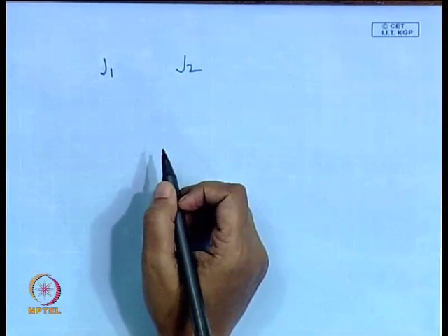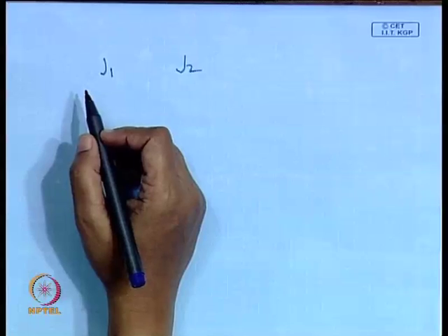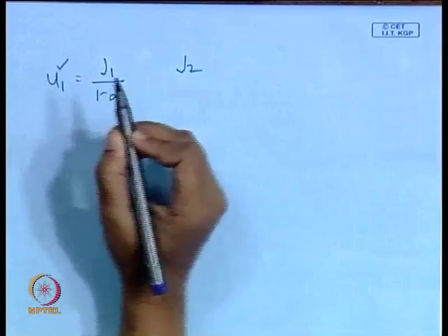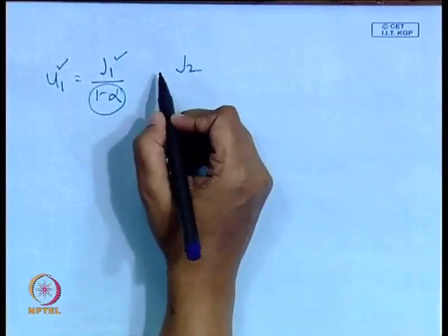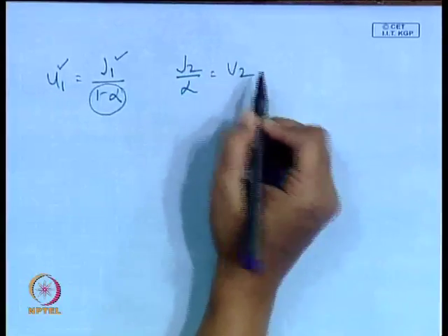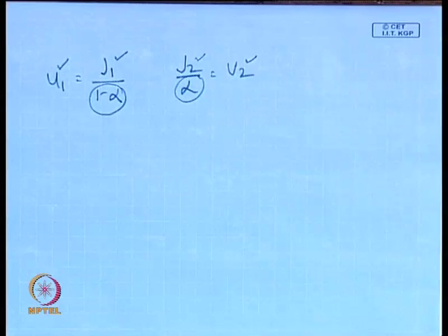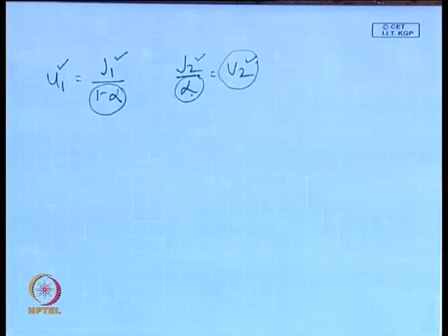The other technique is, we can measure the in situ velocity. It is given by J1 and J2. Suppose by any means we can measure the in situ velocity U1, then we can find J1 and from that 1 minus alpha. Or in other words, if you can measure J2, if you can measure U2, you can find out alpha. So, by some particular localized measurements, if we can measure the in situ local velocity, then it is very easy to find out alpha.